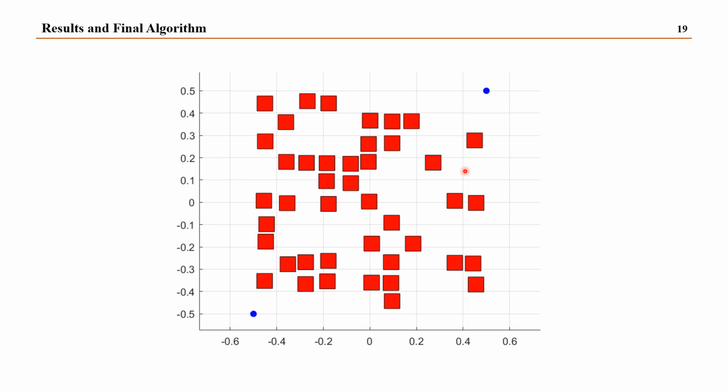So now we're going to apply this algorithm to this type of map. We can see here that the start is here, the goal position is here. Now we can see that this map has many obstacles and could be quite challenging for a classical potential field algorithm and possibly any path planning algorithm, because navigating these tight corners will not be an easy task. So let's see how our harmonic path planning does.